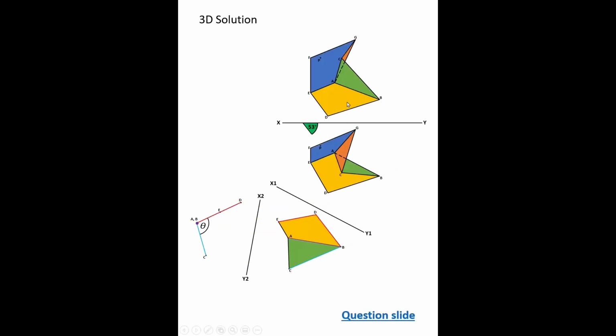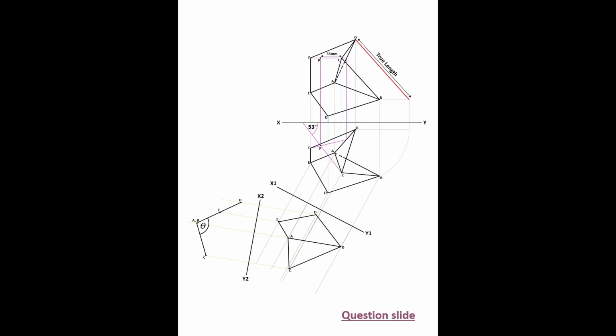And here's our 3D solution that we were looking at. So yeah, 53 degrees, our point P. Yeah, we've seen all that in our 3D model. Let's just appraise the question before we finish up. So the principles that were tested in this question was finding the true shape and true angle of lines and shapes. So the true length was here, true lengths, I guess.